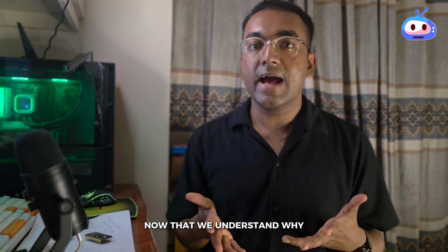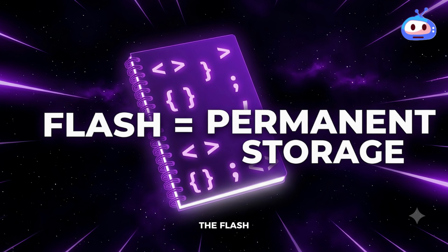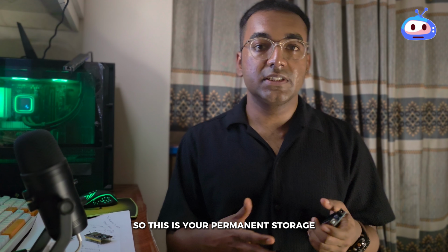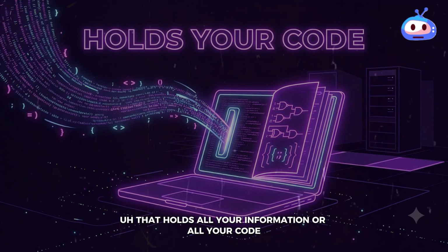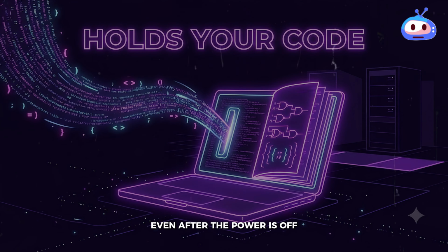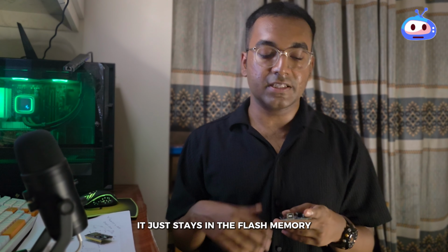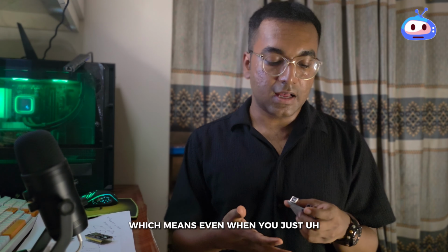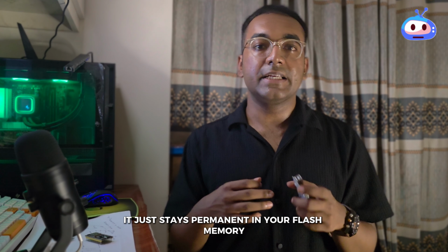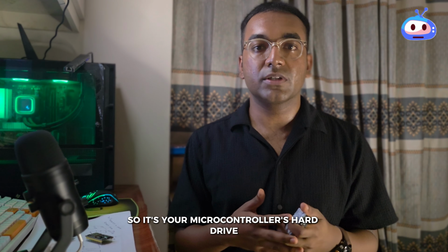Now that we understand why, let's look at the main memory types every microcontroller has. The flash. Think of it like a notebook. This is your permanent storage. When you upload the code, it lives in the flash memory. It holds all your code even after the power is off. When you upload your sketch to the Arduino, it stays in the flash memory. Flash is non-volatile, which means even when you unplug your power source or turn off your battery, all the code you wrote stays permanently in your flash memory. So it's your microcontroller's hard drive.